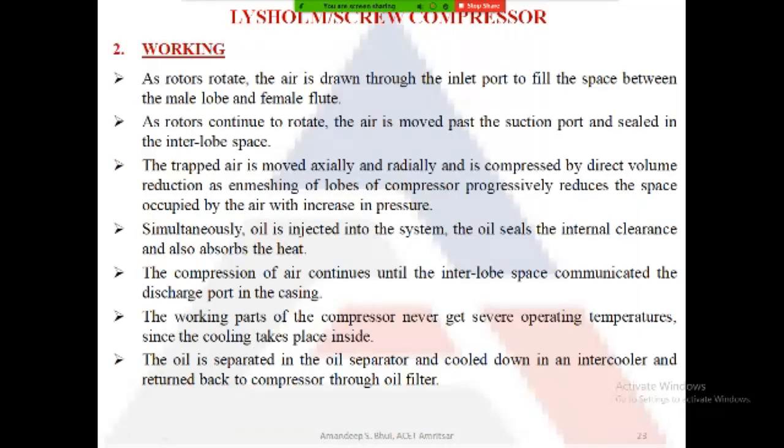So here, as the rotors rotate, the air is drawn through the inlet port and it fills the space between the male lobe and the female flute. As rotors continue to rotate, the air is moved past the suction port and it gets sealed in the interlobe space. Now the trapped air is moved axially and radially.